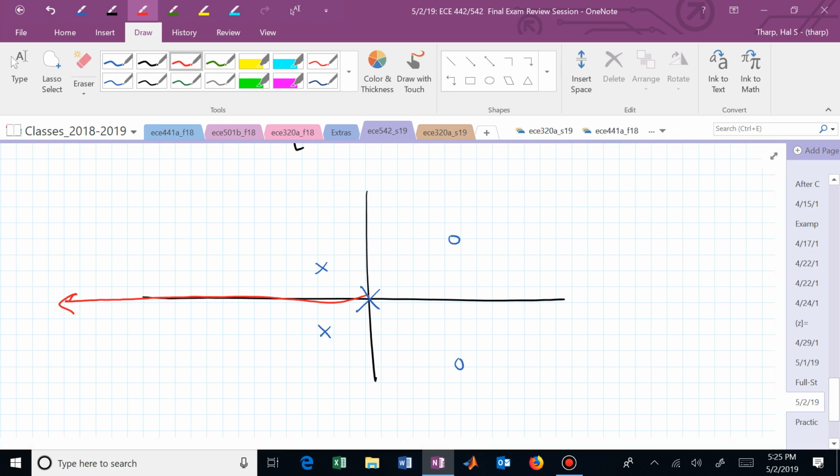What if the arrival angle at those zeros is 185 degrees at the one in the first quadrant, or minus 175? We're now coming in like this. And suppose that the departure angle from the pole in the second quadrant is minus 20. Do you believe that? Do you know how to check it? You could just evaluate k from 0 to -1 and convince yourself there's no relative max or relative min anywhere there, so I didn't re-enter or break away on that segment of the real line. And that's just using the magnitude condition for k.